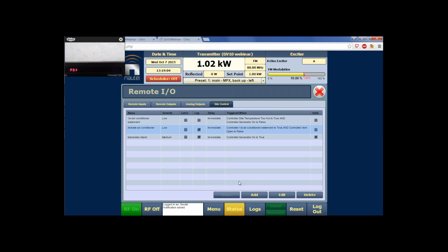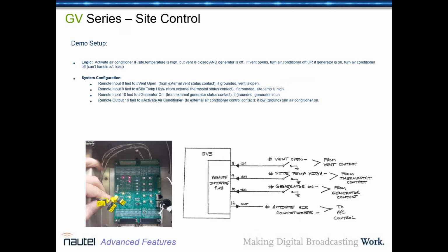Anything more we want to talk about in site control? The challenge with talking about it is, as I said, it's so specific to the sites and what individual people want to do. As I indicated, we are looking primarily at digital inputs, either highs or lows, not analog inputs like a temperature reading, for example. You'd have to have a temperature alarm with a contact closure. Easiest way to do it, just to keep it consistent, is use closures to ground and just wire them in, similar to the very cheap and dirty picture that we've got right here in the diagram on the slideshow.